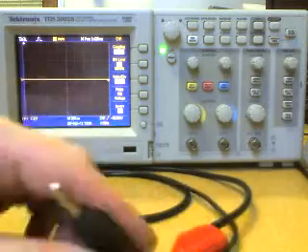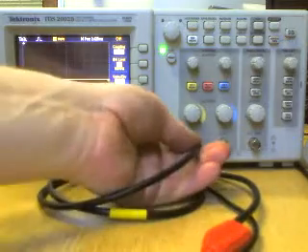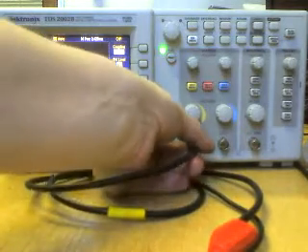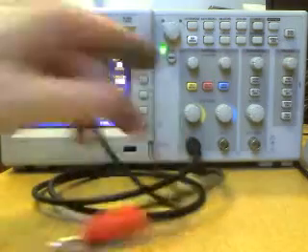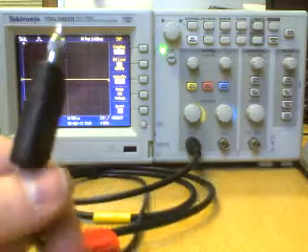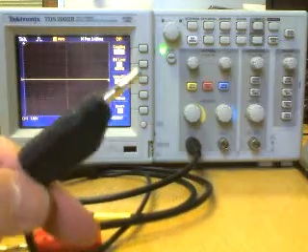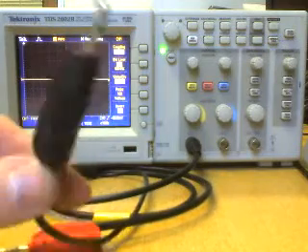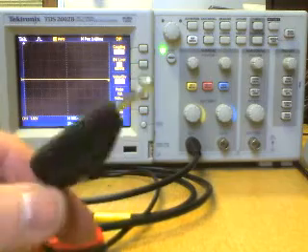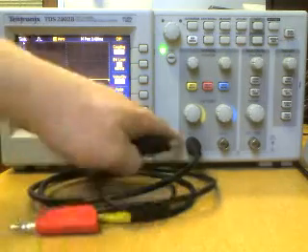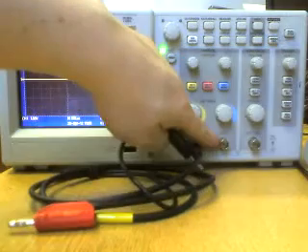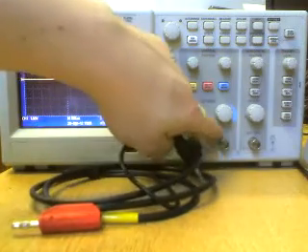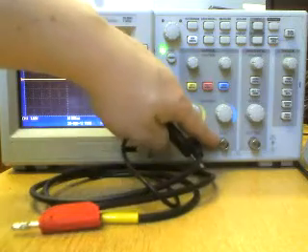Okay, now it's not actually negative or anything like that, but as soon as you plug in a BNC cable, that becomes ground. Okay, this end of the cable isn't connected to anything. I'm just holding it in the air, but it is an actual ground potential because it's connected back here to the outer ring, the outer BNC connector. Okay, the outer shield. This is actually ground.